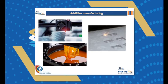The image shown is actually the laser exposing on the material, and it is melting the powder molecules together. SLS printing is also very accurate, and you can get a great representation of a working prototype. The process is a bit expensive, and actually a lot more expensive than FDM printing.